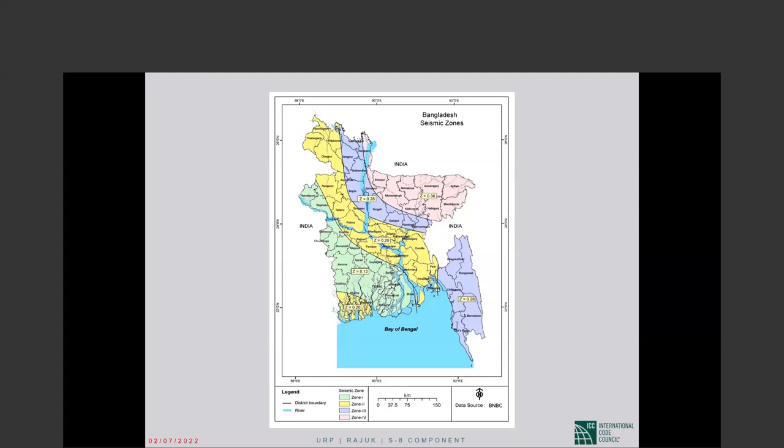Initially, the infill contributes to stiffness, and the building has very high stiffness because of the infill. But then in an earthquake, the infill is among the first to fail. It cracks diagonally, and then it can just fly, even killing people.